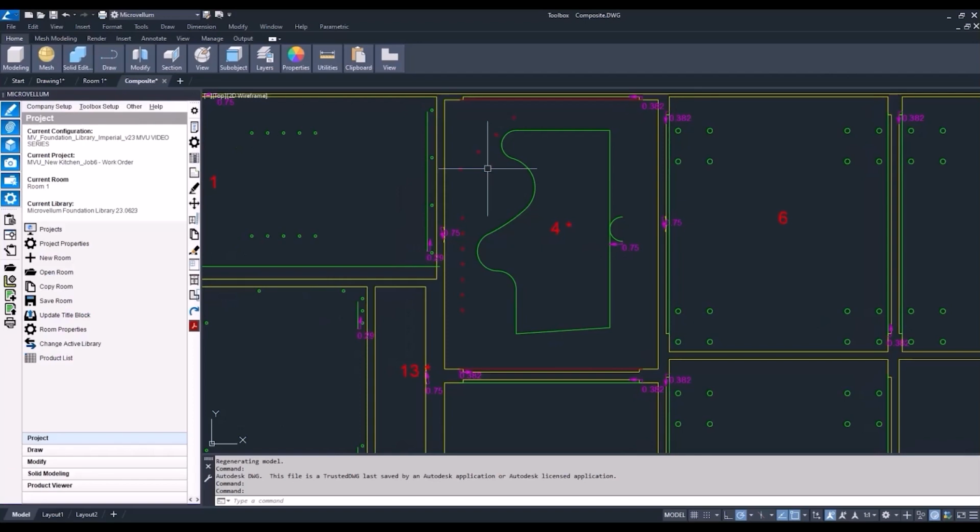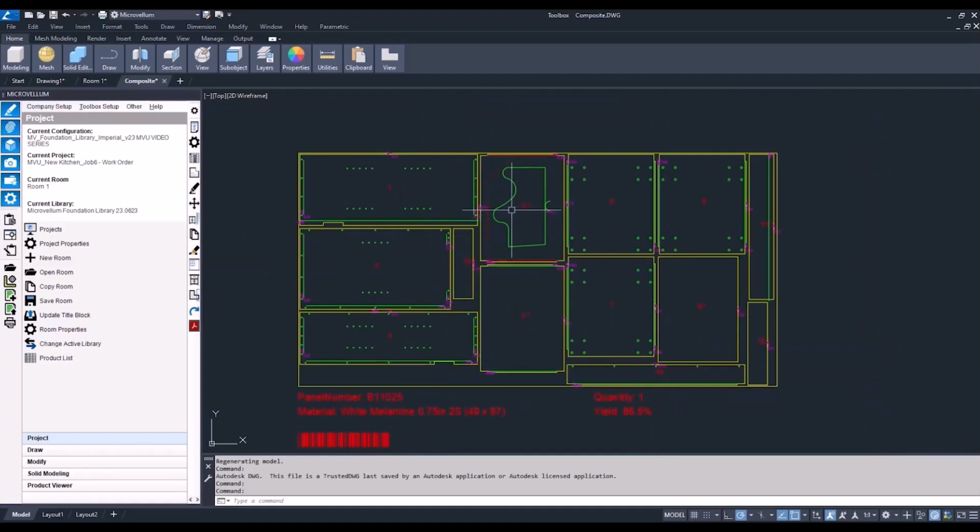We're not going to be able to reach those holes on the back side as it's nested, right? So this becomes a phase 6 part. We're going to do phase 5 machining first, take that part off, and then run our single part phase 6 after everything's done. Now, a little bit about part flipping.